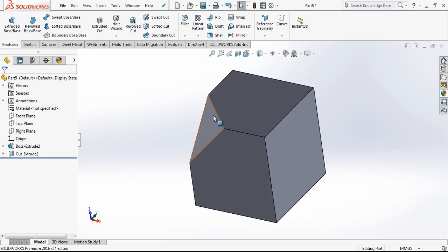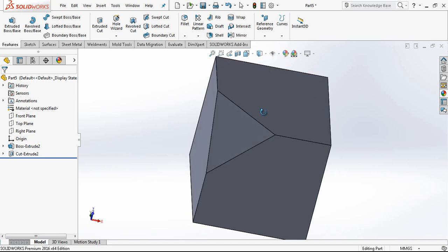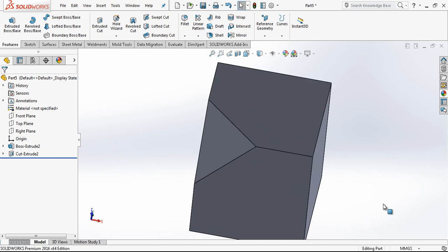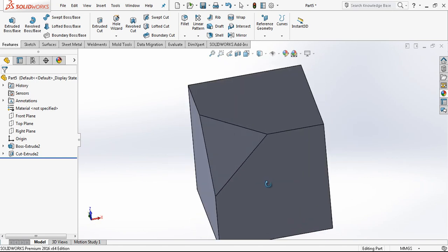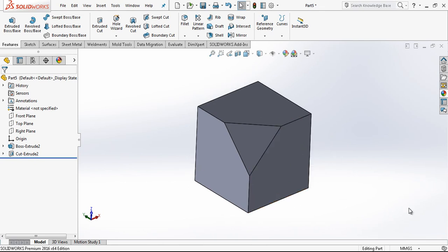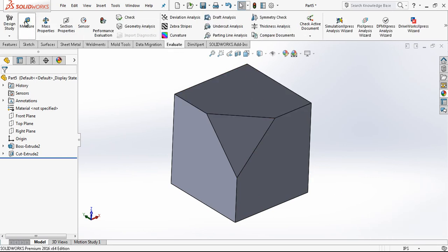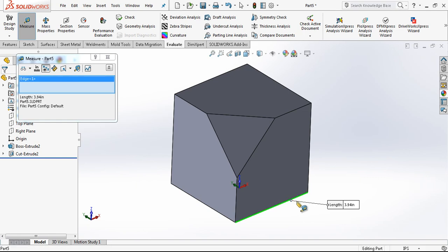Normally you should make this with 2D sketch with direction or with a creating plane here. Now this part is a 100 mm by 100 mm cube. It is a metric system. I'm going to change this to inch system, inch pound second system. When you change simply in this area, your dimensions also now going to be simply inch.